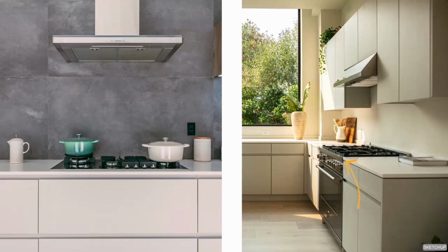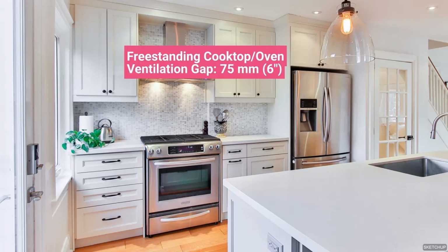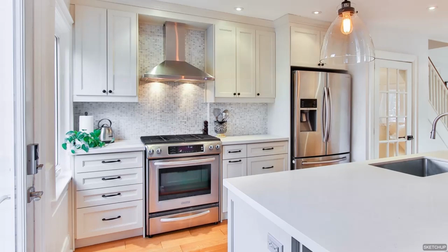For freestanding setups, as I mentioned lastly, check the manufacturer's recommendations for the required ventilation gap behind and on the sides. Typically, it is around 75mm or 3 inches. Consider that in your cabinetry design.